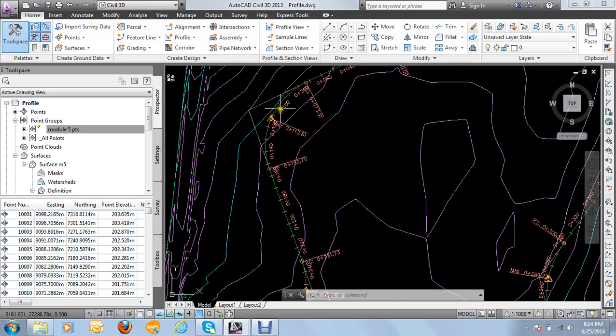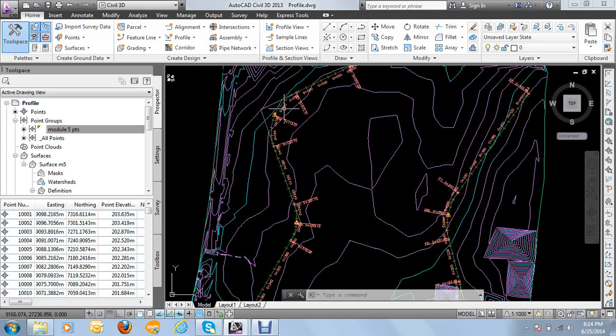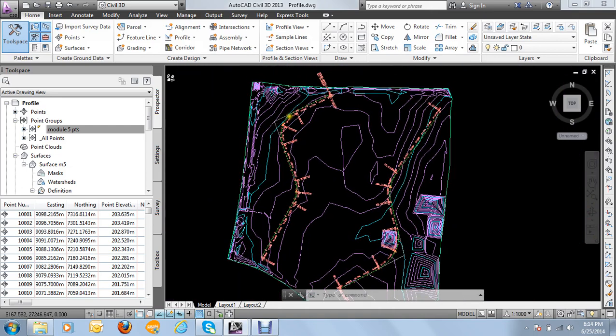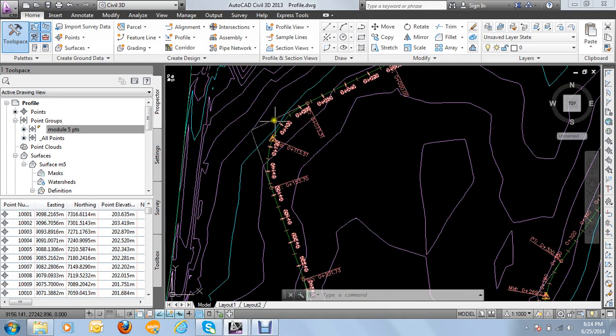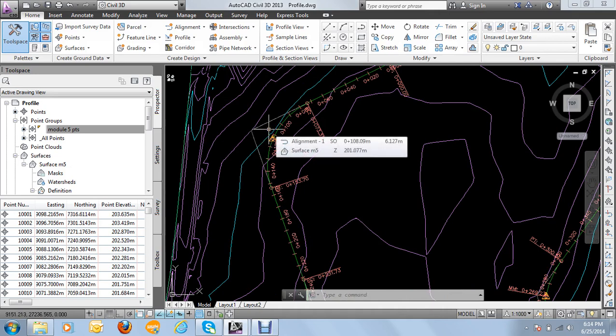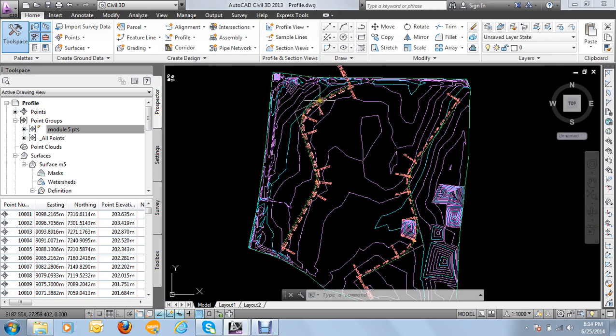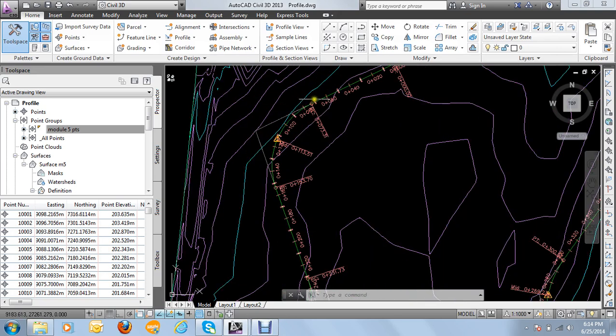Now if there is a problem, and especially in the curves, it's where there is a problem, and in order to remove this problem in the curves, it means in order to remove the warning symbols or to reduce them to that extent, there are several ways you can do it. You can specify different speeds in the alignment, like this one. Maybe starting from a certain chainage where there is a curve, you can just change the speeds.